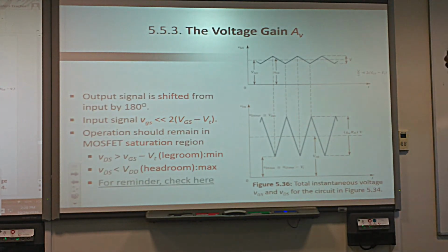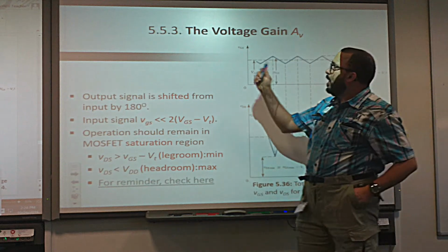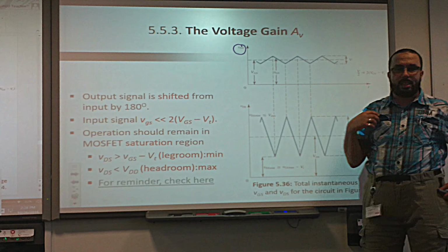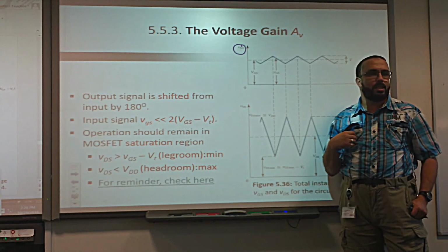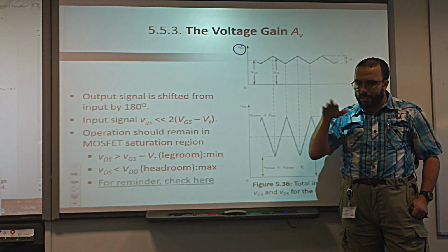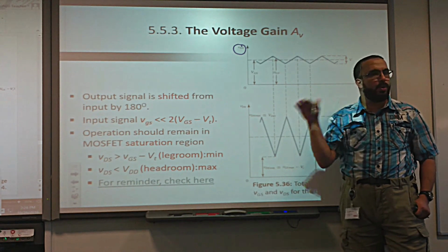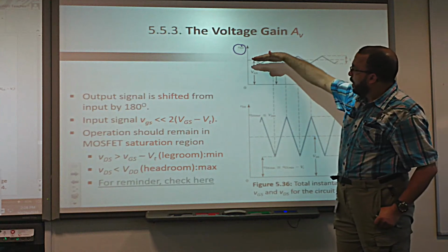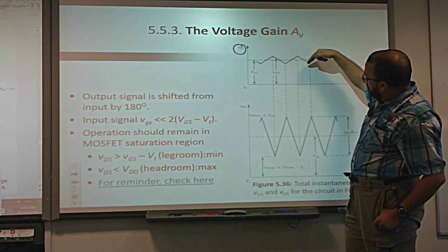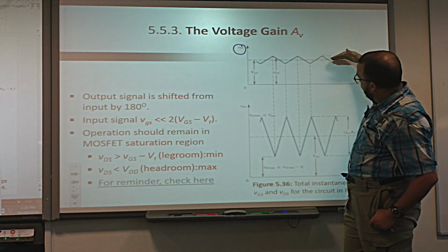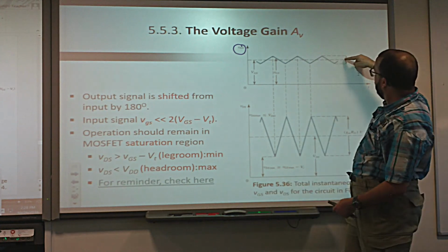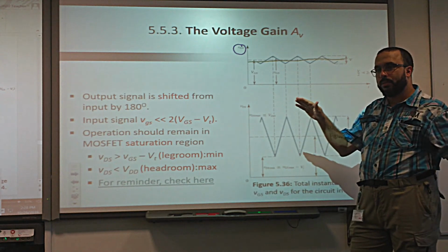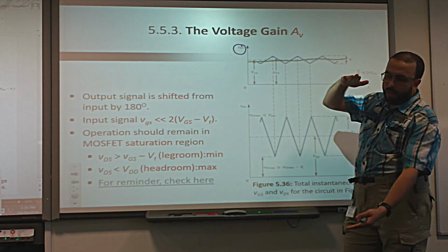Now, when we look at the voltages, this is the input voltage. Of course, this is the instantaneous. Again, we asked about this last time in one of the quizzes. We say that we have an AC signal on top of, or superimposed on, a DC voltage. This is what we mean. It means they have an AC that is sitting on this DC. I'll draw it in green here. It's like a wave in the ocean. There are some waves, but this wave has some depth.